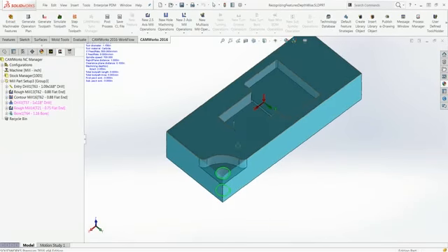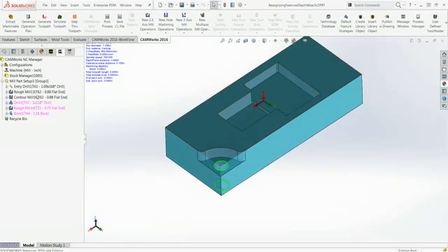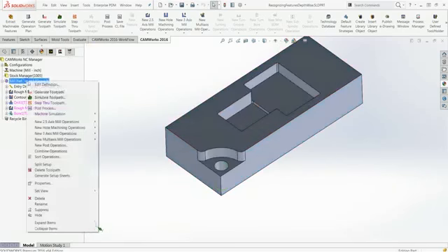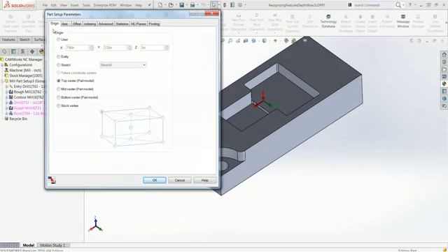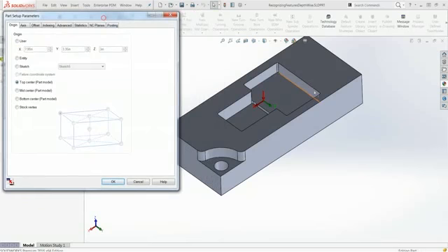And then if I come back to just a milling part, if I go into my part setup inside of my operations tree and choose edit definition, under my origin settings, we now have a new default origin. It's the top center of the part. It used to default to this user position, which could be basically anywhere. So it's now this top center of the part model, where it'll actually default your origin to.